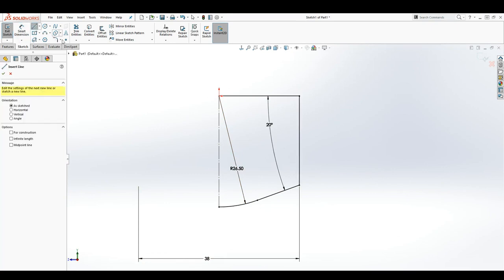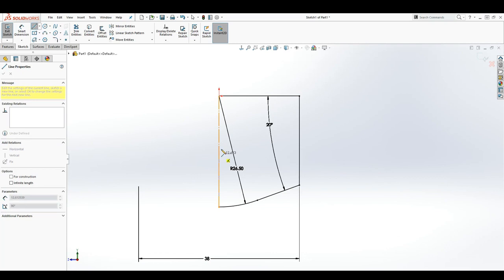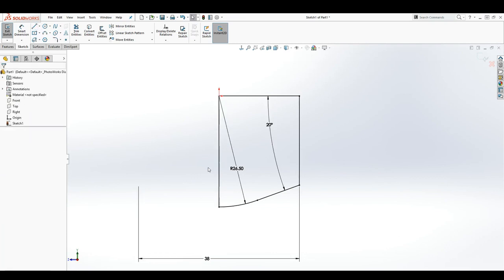And now let's draw a line here. And another thing you need to keep in mind is before you can revolve, your sketch must be closed, meaning you need to have all this sketch all around. The construction line is just something we use. Like I said, you can use it to aid your sketch. I use the construction line to get the 38 diameter.